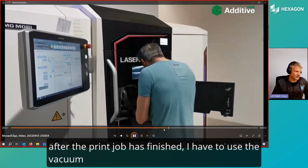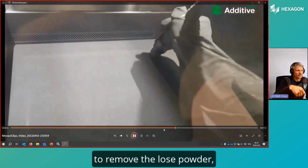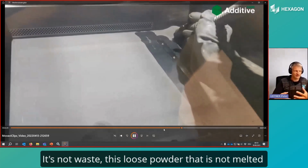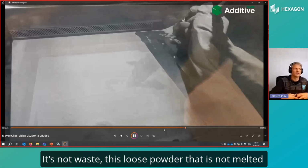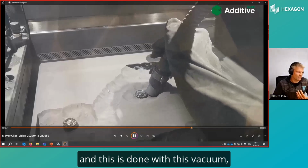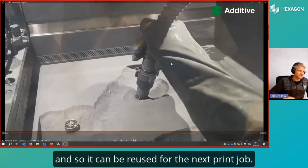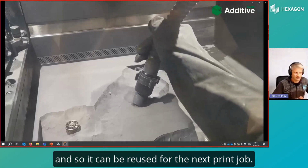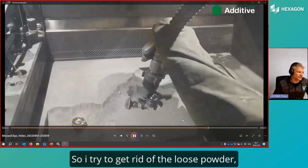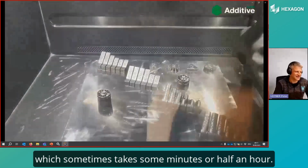After the print job is finished, I have to use the vacuum cleaner to remove the loosened powder, because this powder can be reused in the next job. It's not waste. This loosened powder, which is not melted, can be reused in the next job. And this is done with this vacuumizer here. And it stays in the loop of the machine, so it can be reused for the next print job. So I try to get rid of all the loosened powder, which sometimes takes some minutes or half an hour or something like that.